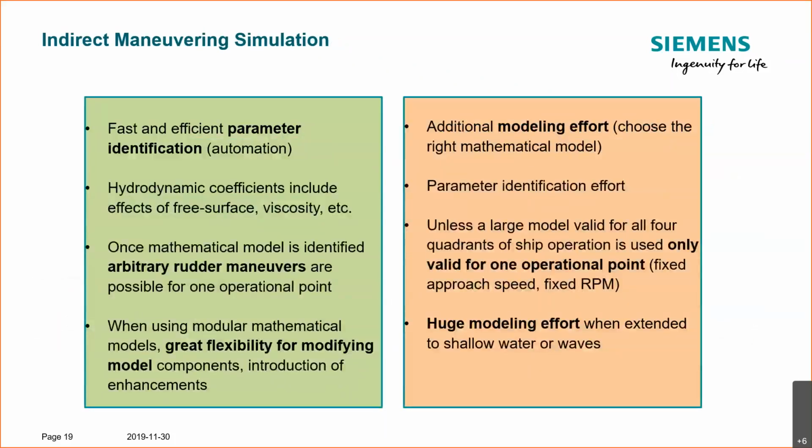What are the pros and cons of this approach versus direct maneuvering simulation? We have a fast and efficient parameter identification, because we can automate all these sweeps that are required to explore the force responses to different yaw rates, different drift angles, and so forth.